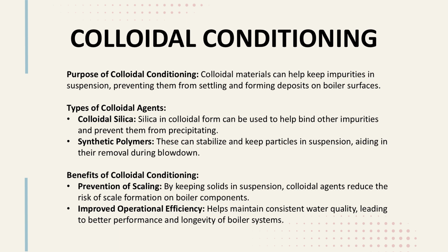In this process, colloidal materials, substances that are finely dispersed throughout a solution, are added to the water. These colloidal agents help keep impurities in suspension, preventing them from settling and forming deposits on boiler surfaces. Types of colloidal agents.